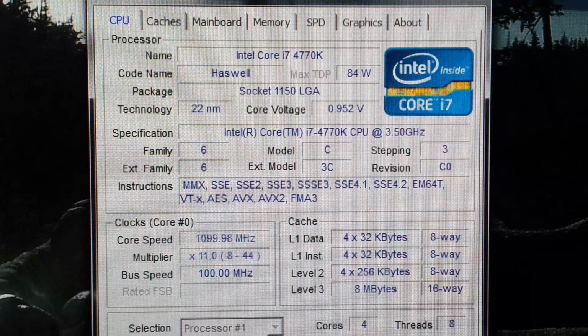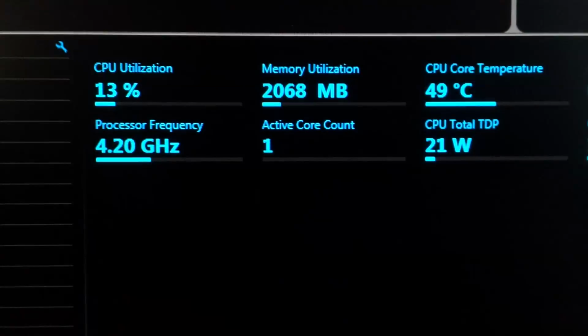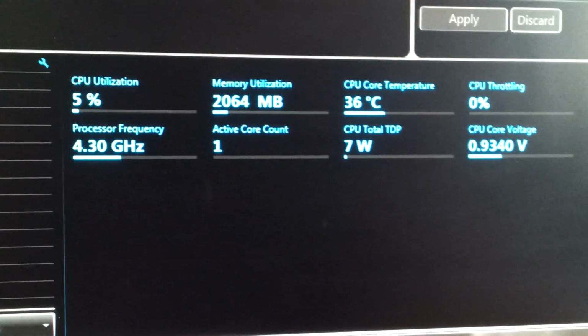And like I mentioned before, it is really jumpy. If I let it just sit here and idle for a bit, it'll be 800 to 2 gigahertz. Because the computer's still kind of booting up, doing a few tasks in the background, that's why you're seeing it jump up to 4.4 once in a while, just like that. So that's normal. This is completely normal. This is how the Intel Haswell CPU idles. Okay? And it's due to the fully integrated voltage regulator.